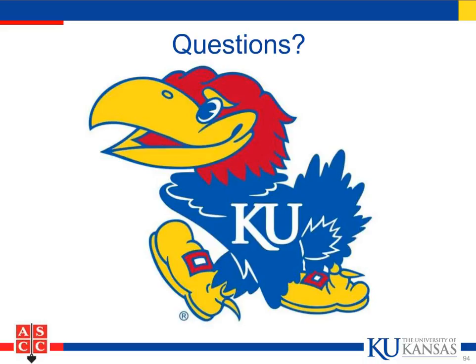Right. I don't know that our cracking is due to that settling so much, but would you recommend, just hearing what I've been saying, that we too use vibrators, maybe have a couple of them going at the same time, immediately before rodding off or immediately after? Yeah, anything you can do to get that settlement to occur deliberately rather than after you do the finishing.